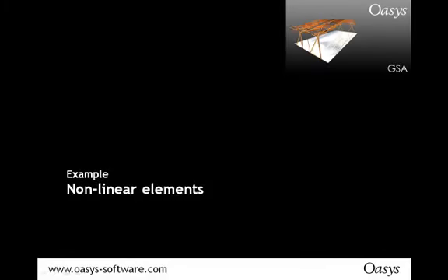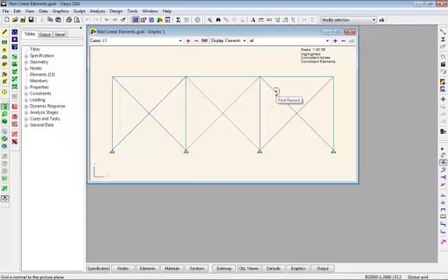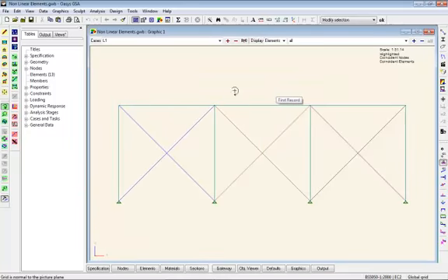Examples of these. Let me open up my model. Here is an example of some non-linear structures. So I've got 3 bays, and I've got first bay cross brace with bars, second bay with ties, third bay with struts, and with horizontal loading on this, and also these main beams are pinned as well, so they won't be carrying moment across.